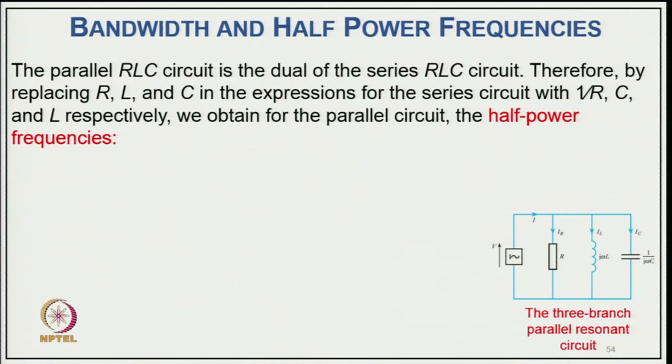Therefore, by replacing R, L, C in the expressions for the series circuit by 1 upon R, C and L respectively, we obtain the parallel circuit.